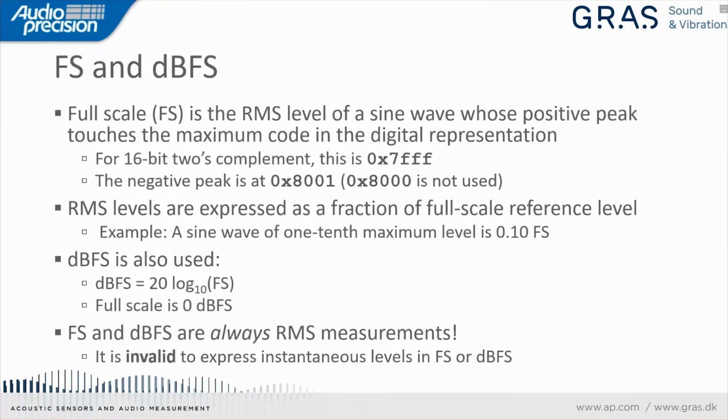The issue with this, if there is an issue, is that not only does that mean that 1 FS or 0 dBFS is scaled to the full scale amplitude of a sine wave, it also means that with the right signal, a square wave, for example, you can in fact have values that exceed 1 FS or 0 dBFS.